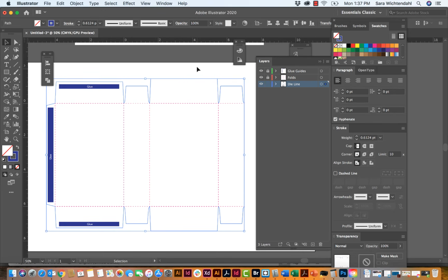And typically you do not want to go over that 1/8 of an inch because every extra little bit of ink that is printed adds to the cost. Ink costs money. So if you're having artwork way, way, way over the die line and it is getting printed in commercial printing, that can drive up the cost. So you don't want to needlessly drive up the cost of production for artwork that's never going to be printed or seen. It's just going to end up in a trash heap.